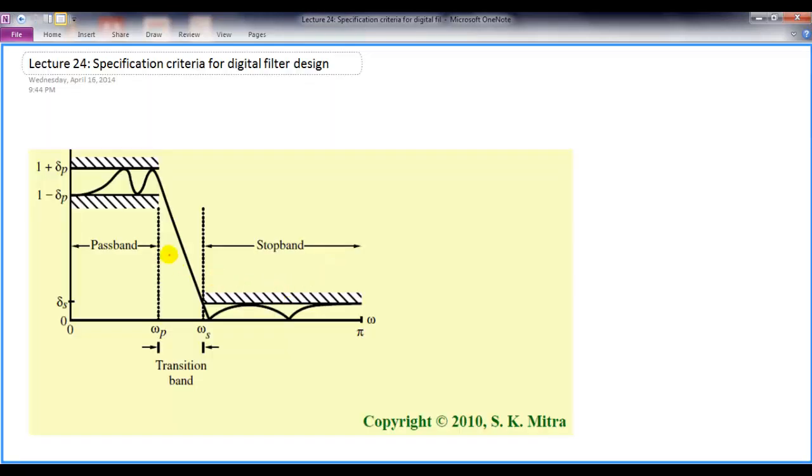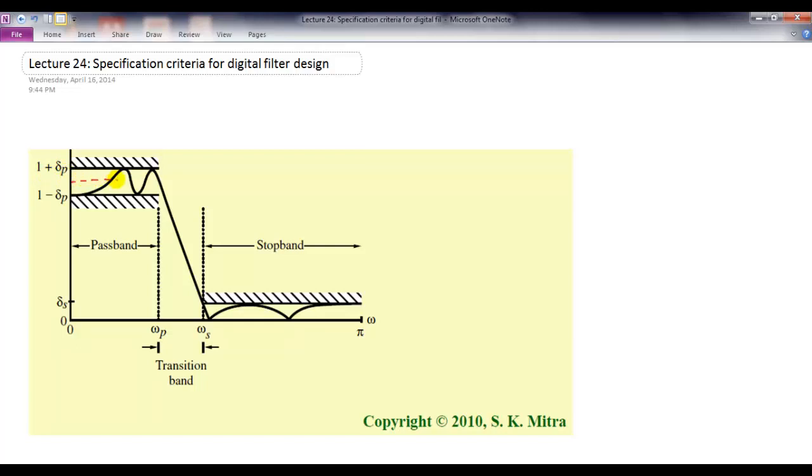So this is just a demonstration of what I just talked about earlier, the plot I showed you. This is for the low pass filter. I want you to be aware that the same statements could be made for a high pass filter, in which case the stop band and the pass band definitions will change. Basically, anywhere where your filter is supposed to stay away from 0 is called a pass band, and anywhere where it is supposed to stay close to 0 is called the stop band. And in general, you want your filter response, so this point is 1.